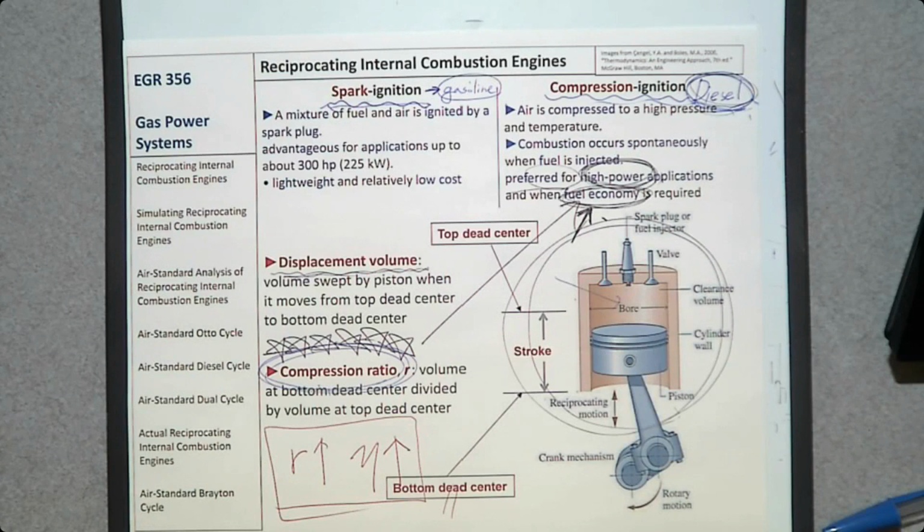The piston is moving up and down. Why is that? We want to have higher compression. Then we can increase the compression ratio, so we can save fuel. So the way that we design an engine depends on where we are going to apply it. So it's going to be a balancing between the fuel economy and the power output.